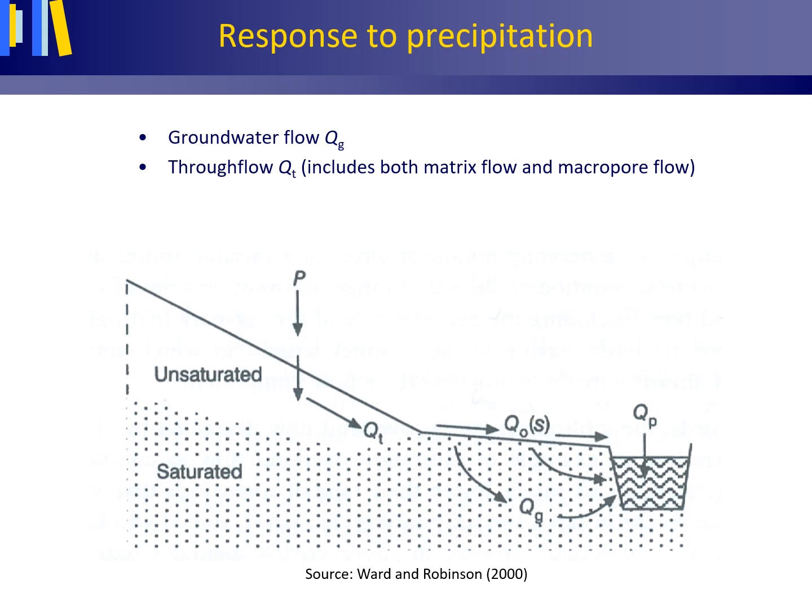Because the overland flow stems from the upper soil profile being saturated, overland flow produced this way is called saturation excess overland flow, or in short, saturation overland flow, in Dutch, verzadigingsoverlandflow. Saturation excess overland flow is sometimes referred to as Dunnian overland flow, after Thomas Dunne, professor in geomorphology and hydrology.